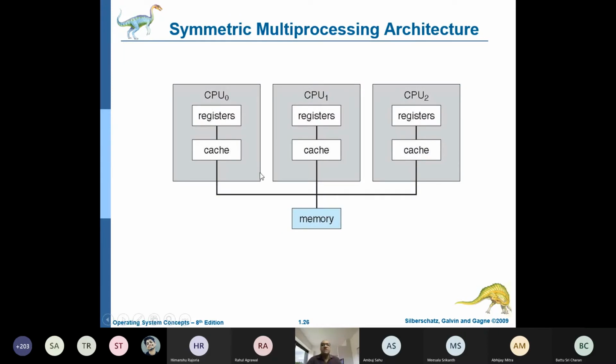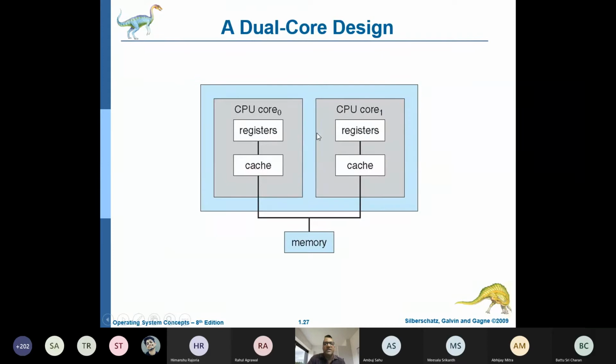the multiple CPUs or processors are on separate chips, and the coordination or communication between these processors has to be done across the chips, using interconnects. With that, the communication or the data transmission has to take place. Whereas here, since both are in the same chip, the communication between the processors will be much faster compared to the earlier structure.